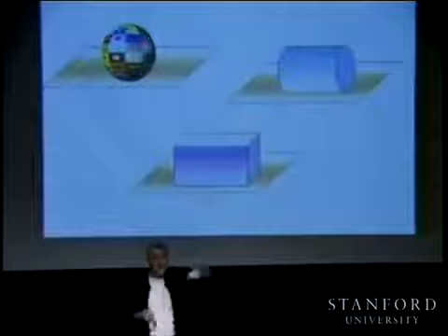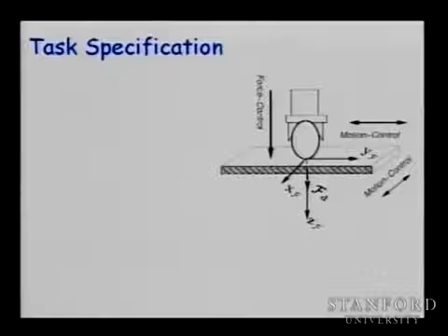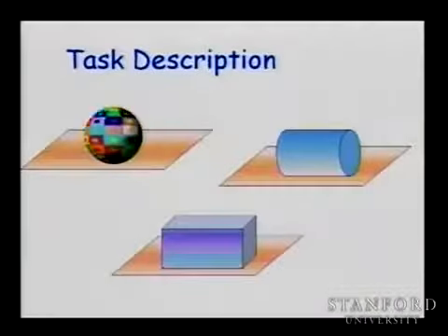Because if I'm pushing here or controlling this moment, I still can do it. I can push with 10 Newton, 20 Newton. So the degree of freedom just went to the space of force control. So in those contacts, if you are talking about controlling that variable, the force, then you didn't lose the degree of freedom. It went just into the constrained space, and you can control now that force. And we can now describe the directions and the relationship between the two and separate the spaces.